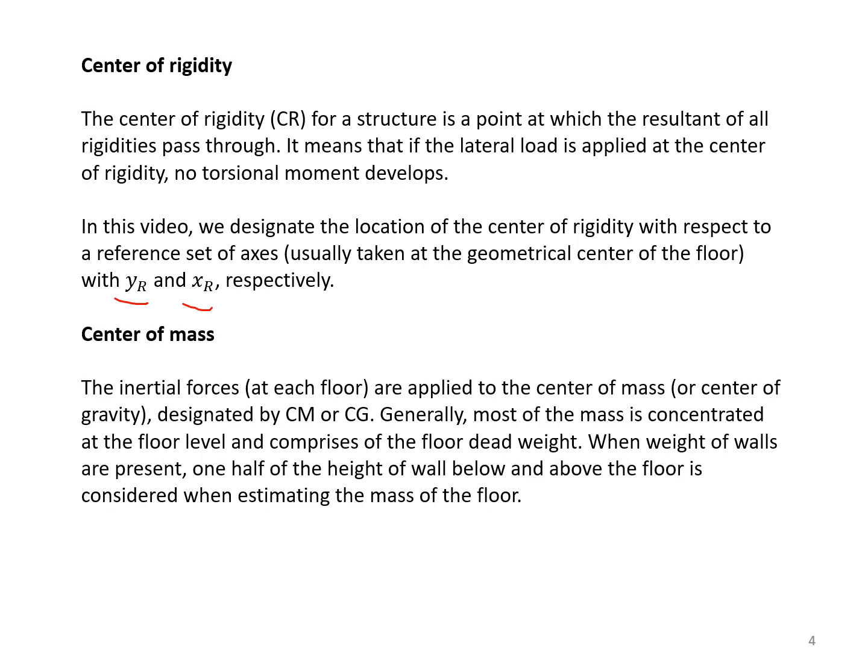Center of mass. The inertial forces at each floor are applied to the center of mass or center of gravity, designated by Cm or Cg. Generally, most of the mass is concentrated at floor level and comprises the floor dead weight.